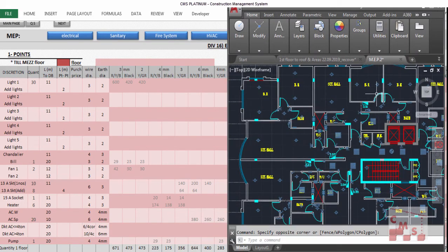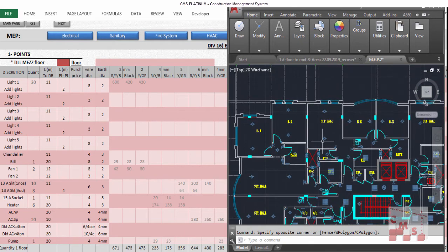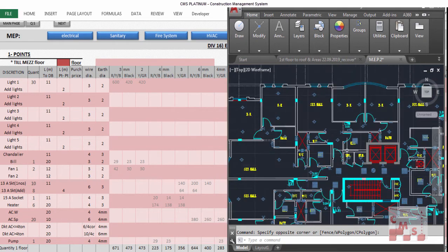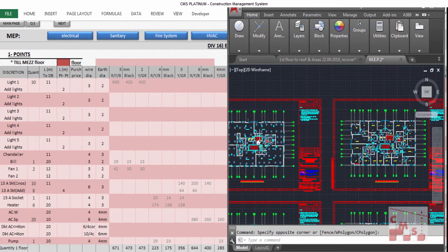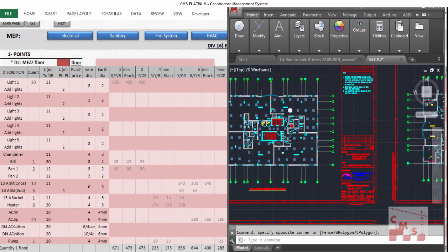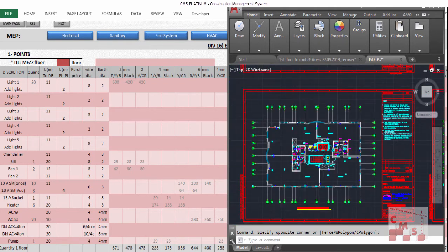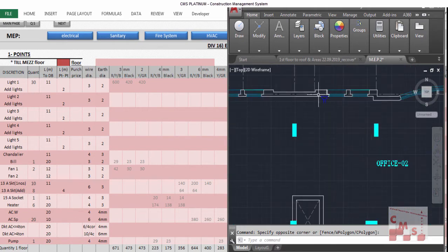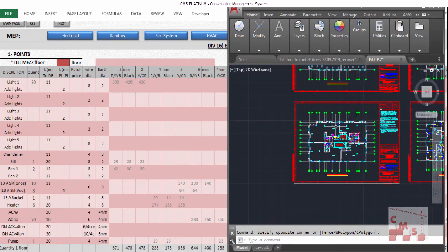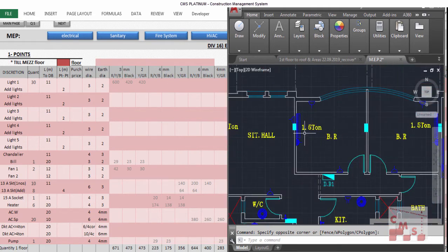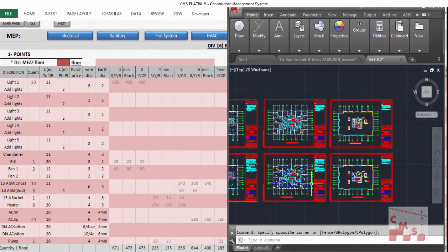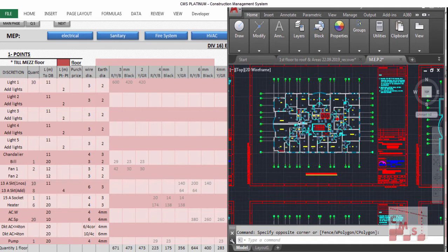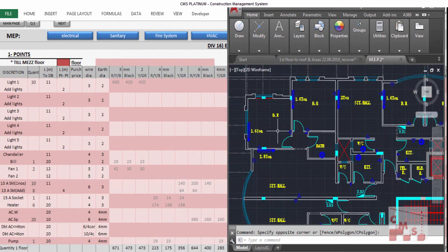Electrical work starts with the lights, showing the locations of the lights for the whole building or all the floors. It will be repeated according to the number of floors. Like this, it's showing the lights, so those are the lights drawings. You will also have the power drawings, which have the location of the sockets for each floor, and the AC drawings, which have the locations of the AC and the routes of all the AC and the AC ducts, and other power related to the pumps and other electrical items.